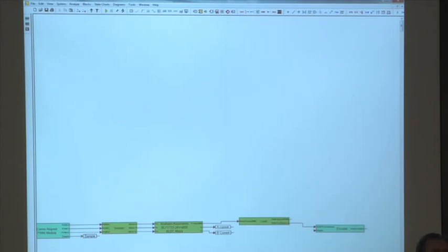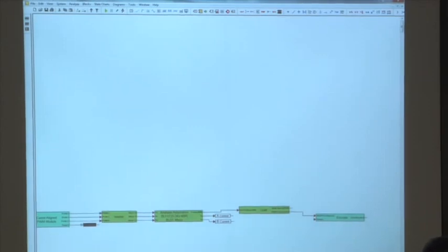You can also see that the encoder signal needs to be sampled. So we're going to find one of those sample signals again, select it, Control-C and Control-V, and paste that on the input of the encoder module. All right. Now, we're almost ready to close the loops.